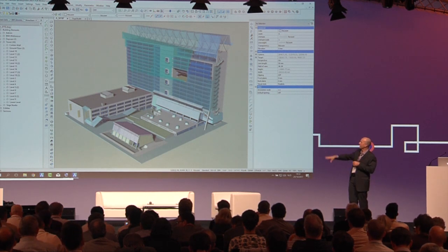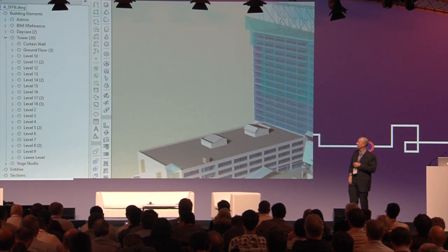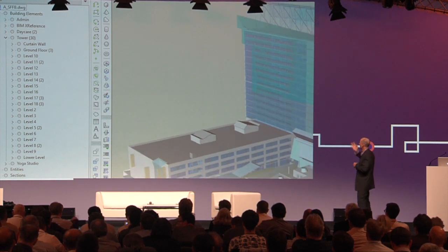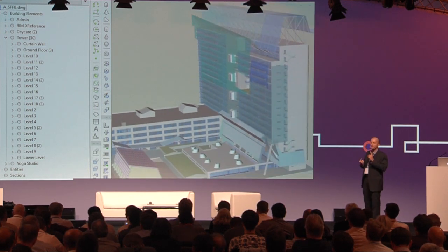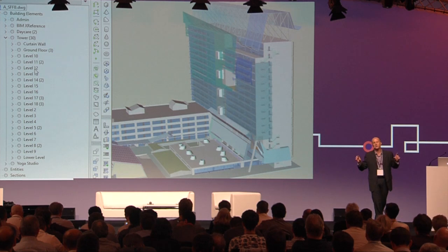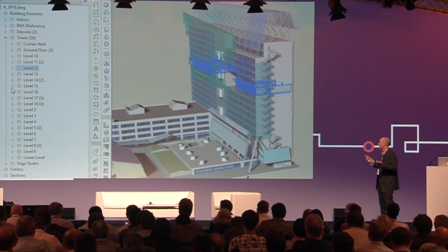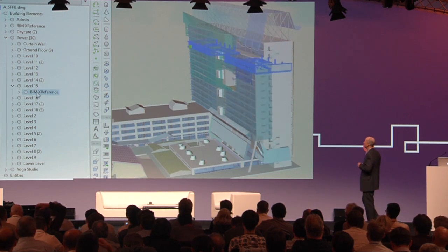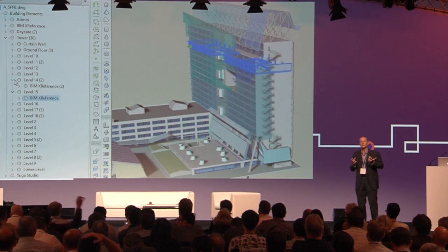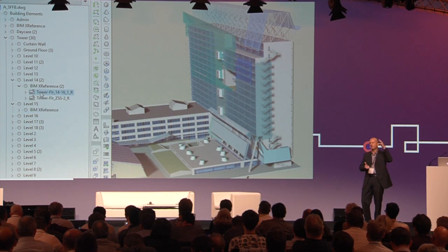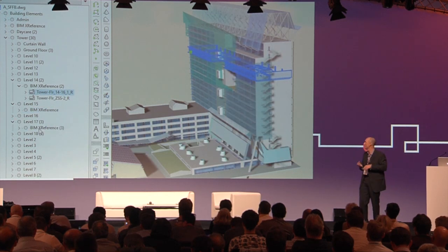So on the structure browser, under building elements, we have the different buildings. And Jacob's expanded the tower. And so by clicking on this, we might do some of the XREFs as portions of a floor that we can reuse multiple times. They might be unique floors. They might be in the center section. There's a group of 3 floors.